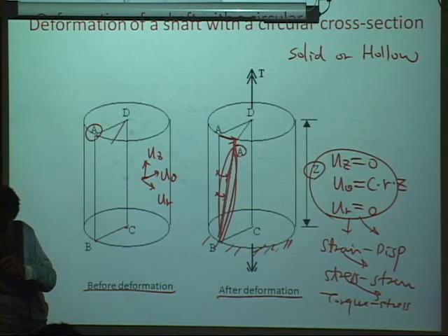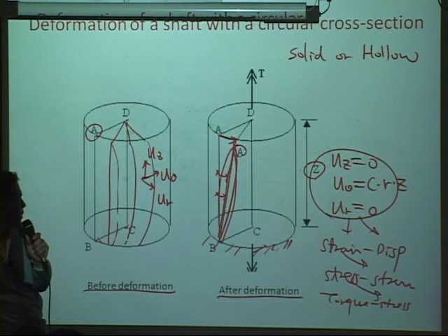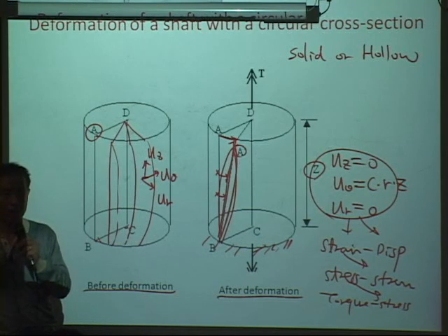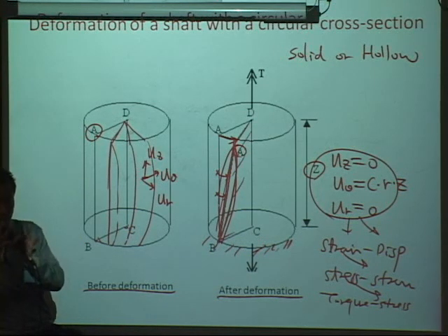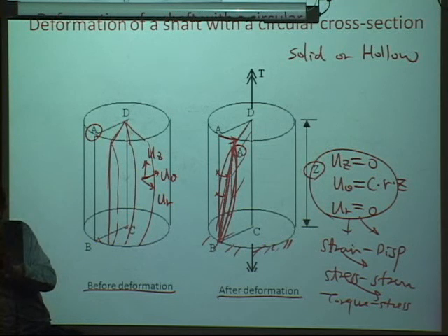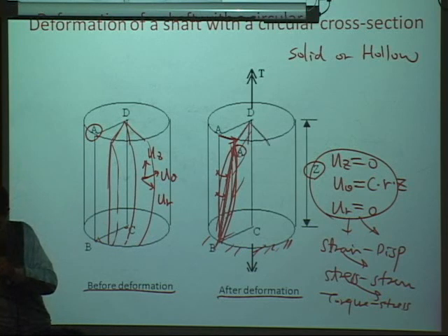Well, this story will be a little bit long, but let's say it is curved like that, then all the elements should curve like that, right? But that contradicts compatibility. This has to be straight so that every portion has an equal displacement. If it has a bend like that, then there won't be compatibility between each part.